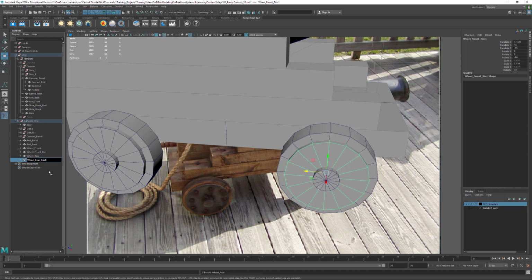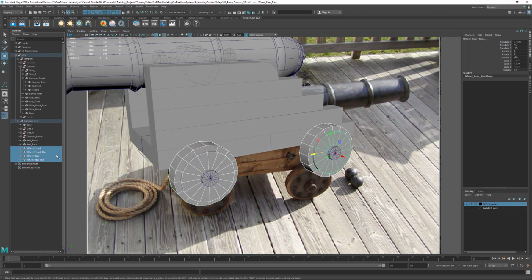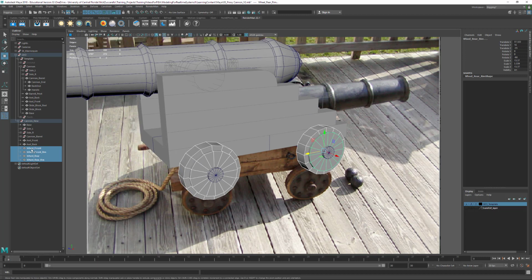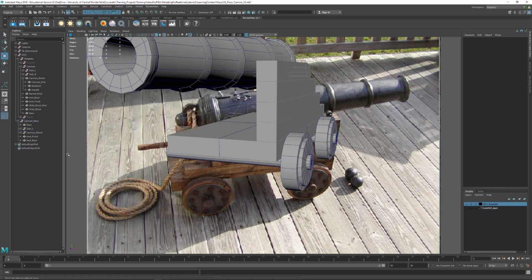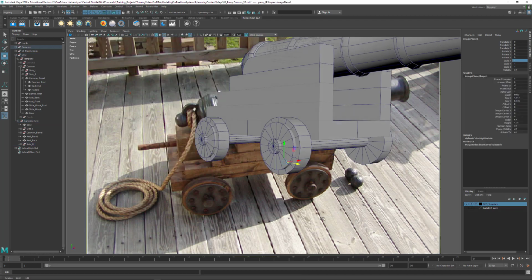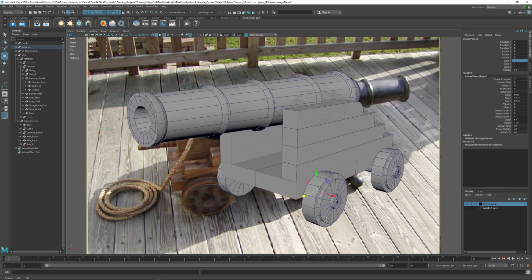It's pretty important that you name your object something that means something. You can see up here I didn't pay too close attention to that and made it a little bit difficult to figure out what some of these things were. So if I take all these wheels and middle mouse drag it into the side left, we can just get rid of the side R, and we can keep doing this process where we take the side L, duplicate it, Control D, and call this side underscore R like that, and just give it a negative scale in X. And you can see now very quickly we've got a left side and a right side for things, and that's starting to work pretty good for us.